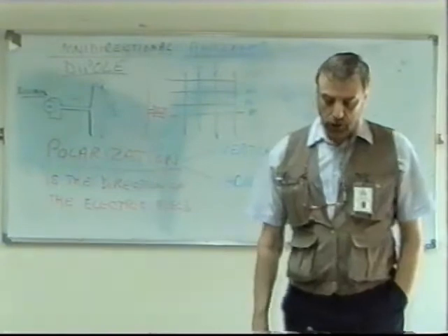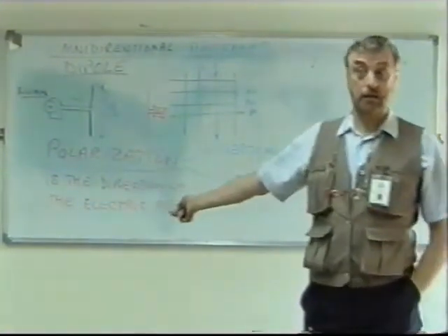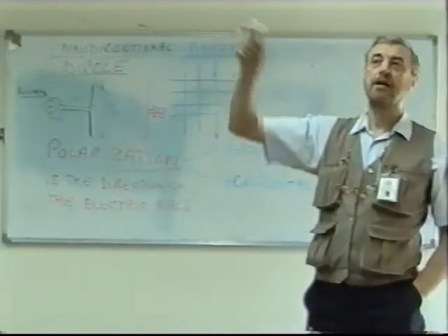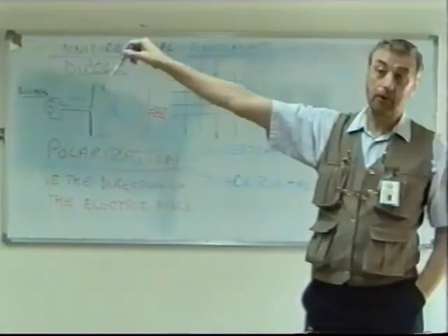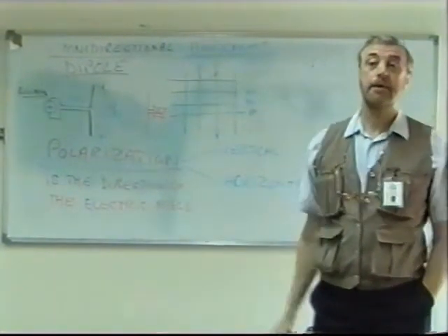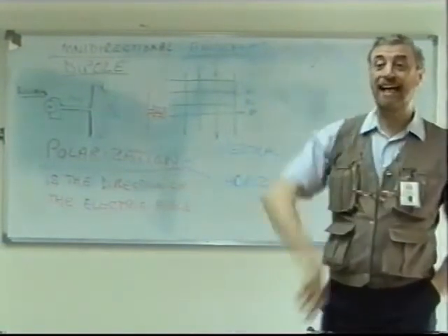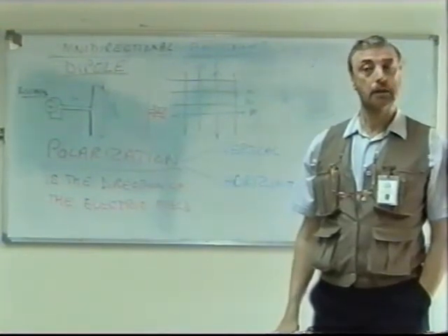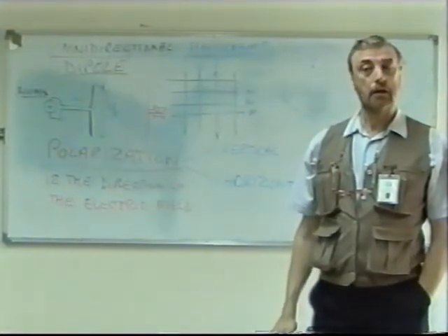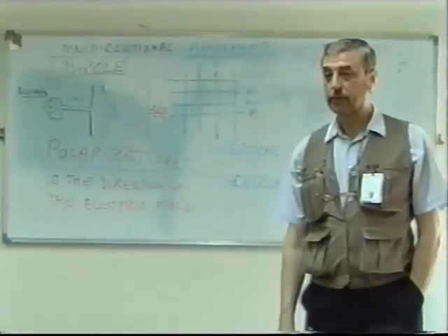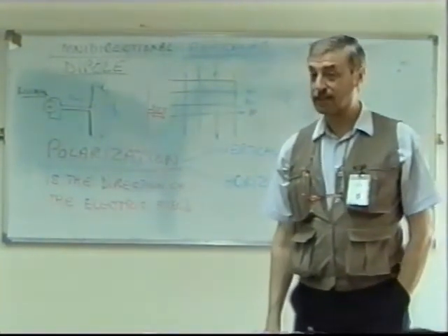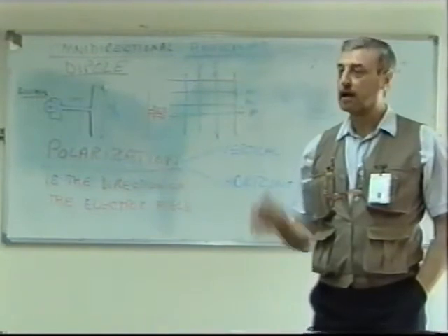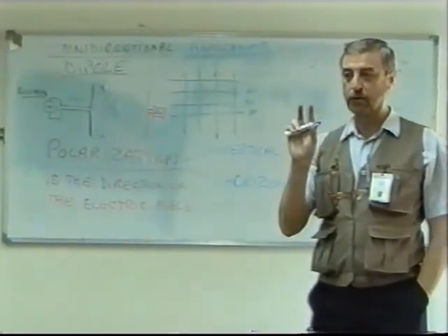Well, yes, they do, as I described here, but it's very large. You're talking about receiving HF, are you? Transmitting HF, yes, we do. At the airport, we have these what we call log periodics. They're dipoles, but omnidirectional. Remember, a different length for each frequency in the HF band. Actually, it's directional. It's not omnidirectional, but it's directional for a different reason because it's using many dipoles. I haven't covered that reason yet. I'll give you a note on this in a minute.